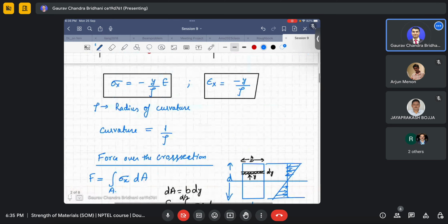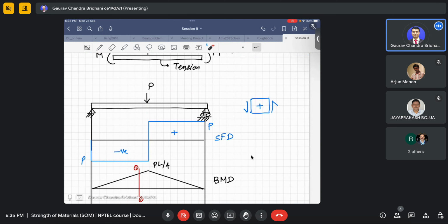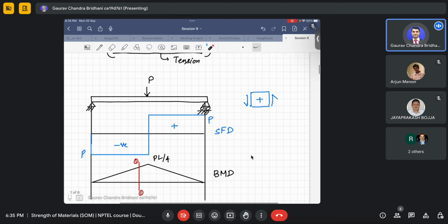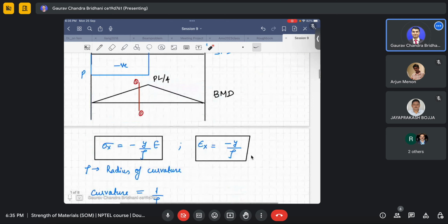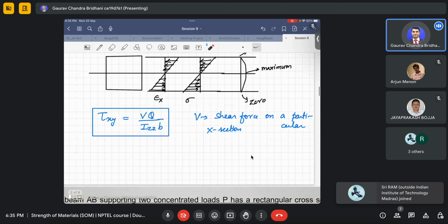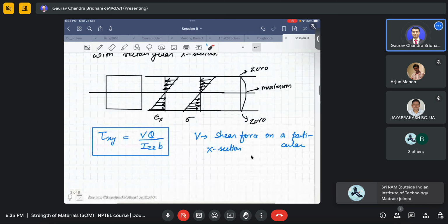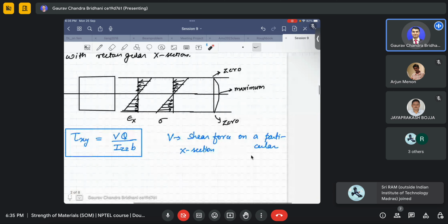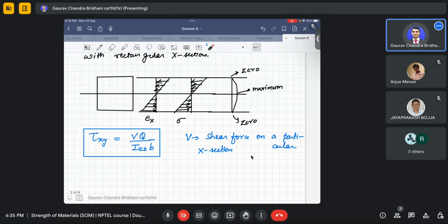You can see the shear is varying. Here actually it is a constant, but if I give some other loading where shear varies, you can have different values of shear at different cross sections. What interests us most is that we tend to find it at the maximum places. Here at the support the shear remains maximum, and in this case it remains the same throughout the length also. So our interest always remains to find wherever it is maximum. We generally use the maximum, where V max is coming.